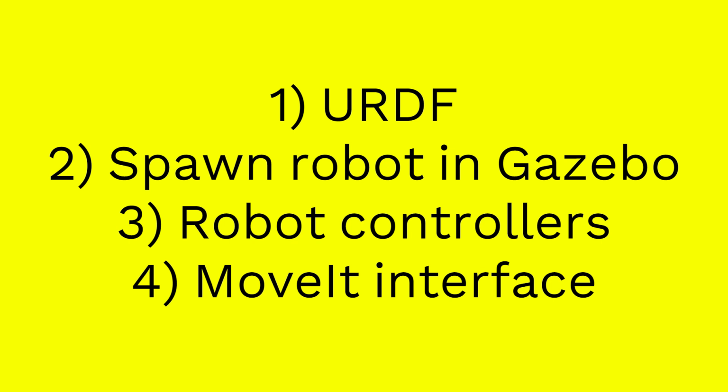Let's start, keep it simple, in an empty world. Then you're going to make some modifications in the URDF file, because you need to get the namespace of your robot, very important. Then make sure that all the hardware interfaces are going to be the effort controller, for sure, if you want to use an effort controller as the interface, and then make sure that the ROS control plugin for Gazebo is loaded correctly.